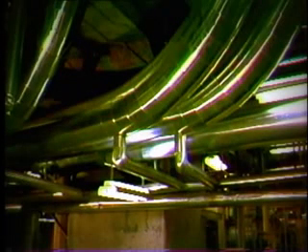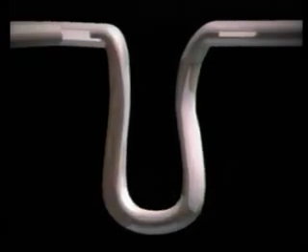The most important thing in this maneuver is to make sure that all of the water is discharged from the drain lines to prevent any water from being carried along with the steam and damaging the turbine when we start up. The piping must undergo considerable expansion as its temperature is raised from, say, 200 to 1,000 degrees Fahrenheit. The runoff pipework is designed with deliberate bends and turns to accommodate the expansion between two fixed points, that is, the boiler outlet and turbine inlet.